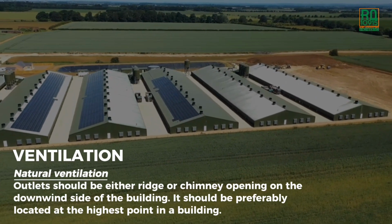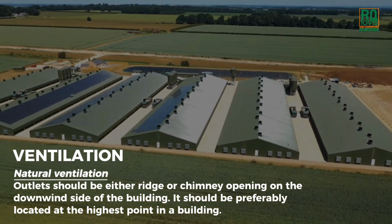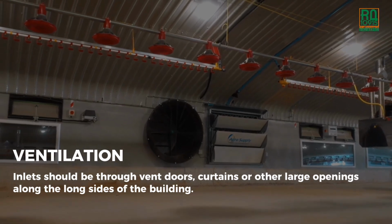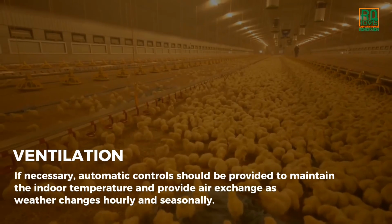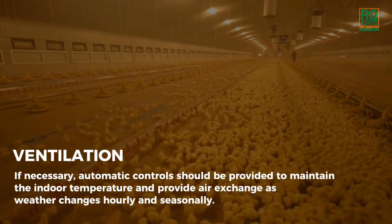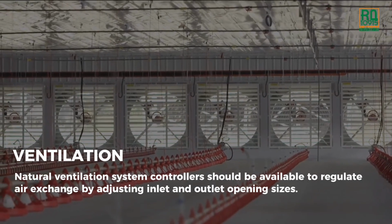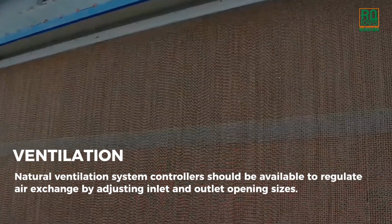Ventilation. Natural ventilation. Outlets should be either ridge or chimney opening on the downwind side of the building. It should be preferably located at the highest point in a building. Inlets should be through vent doors, curtains or other large openings along the long sides of the building. If necessary, automatic controls should be provided to maintain the indoor temperature and provide air exchange as weather changes hourly and seasonally. Natural ventilation system controllers should be available to regulate air exchange by adjusting inlet and outlet opening sizes.